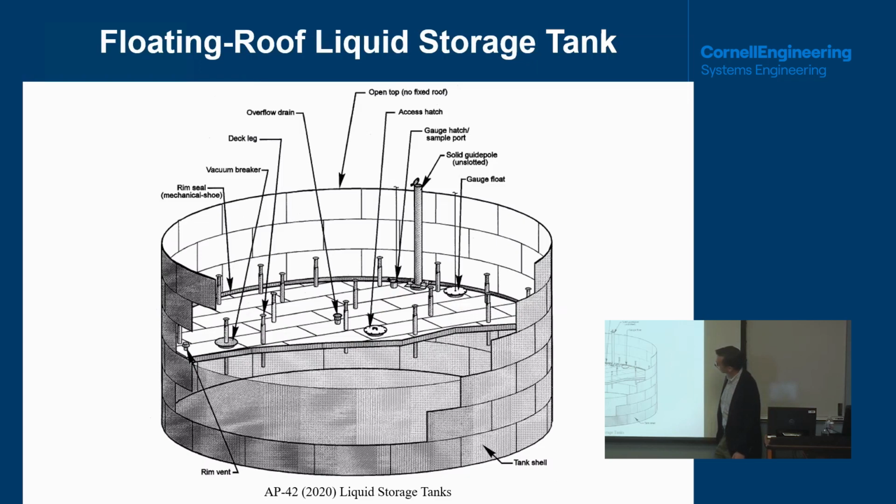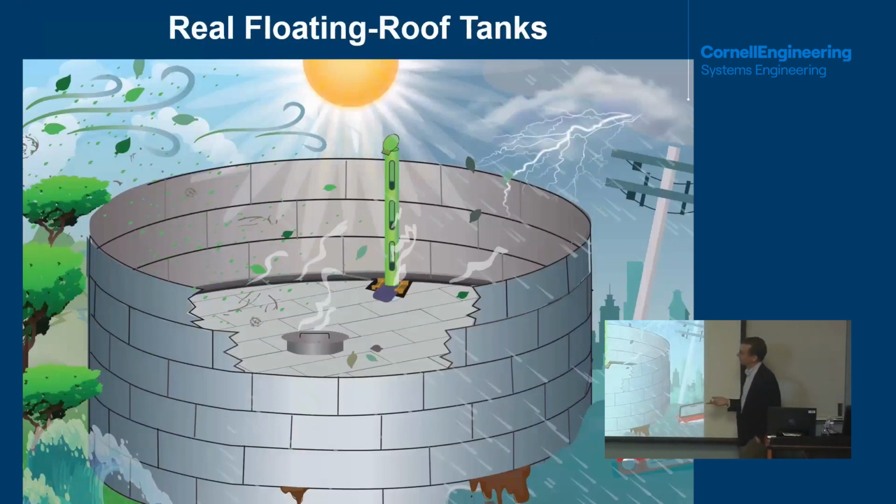You have breathing losses. It gets hot during the day and then cool at night, and the difference in temperature leads to emissions. And then finally, all these deck fittings, you can see all these items in here, and there are rim seals along the edges. All these things can have leaks of emissions as well. It's not going to look like a real tank, but what real tanks deal with is all of these emissions coming out of here, and they could be looking at leaks coming out of the tank.